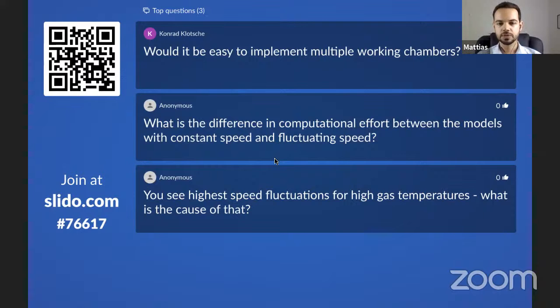Okay, so that graph was created using the simpler compressor model, which is less precise regarding the bearing simulation, but is capable of simulating the valves and the mufflers regarding different conditions of the compressor. And the fluctuation speed is a response. Of course, the speed fluctuation is on one main side a consequence of high loading on the piston, right? So having higher condensing pressures, you have a very high effect on loading. So there is where you have the highest loads.